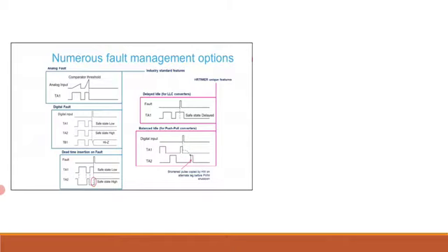The HR timer, however, offers some unique protection features. For LLC converters, the delayed idle maintains the current pulse on the output, and the fault state is entered only after it is completed. That's the one marked in pink. For push-pull converters, the balanced idle mode guarantees a perfect balance between the two output pulse widths when a fault is triggered before the converter actually enters the fault state. The output pulse, which is shortened by the fault, is automatically copied on the alternate output before stopping operation.